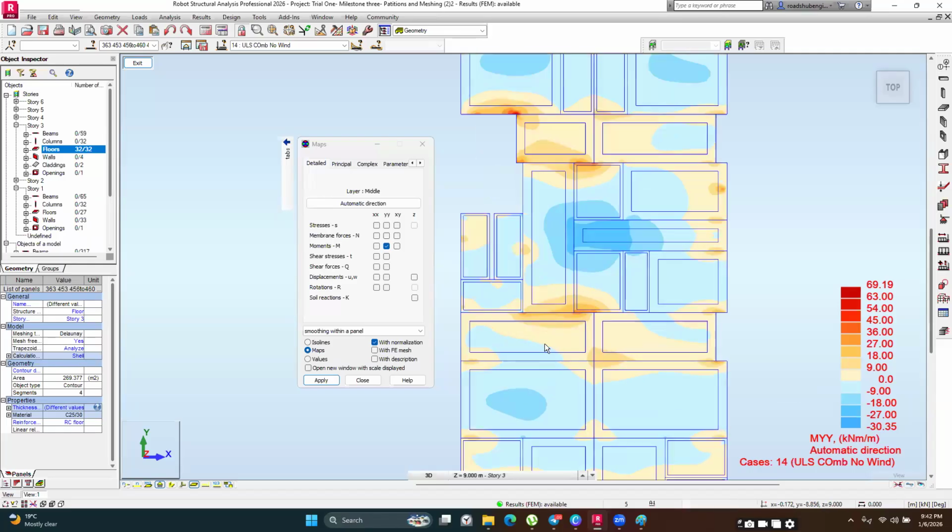If you look at this, if you had not modeled the entire slab, it may be difficult to choose to place your top bars up to this particular point here. But now since you have your result here, you're going to choose to have your top bar along this entire point here. So there's that, it's going to play a role in that.